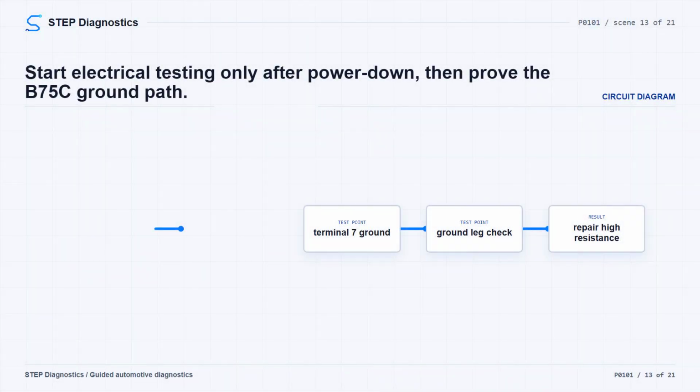Before resistance testing, remember that it may take up to 2 minutes for all vehicle systems to power down before an accurate ground or low reference continuity test can be made. Turn the ignition and vehicle systems off.